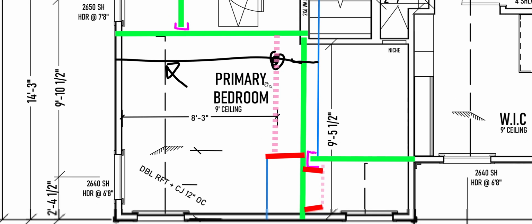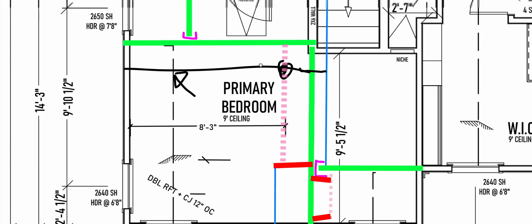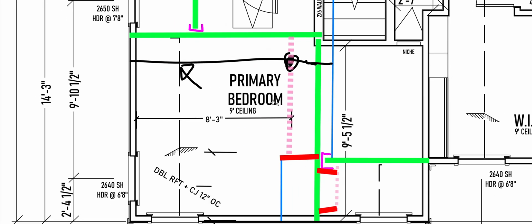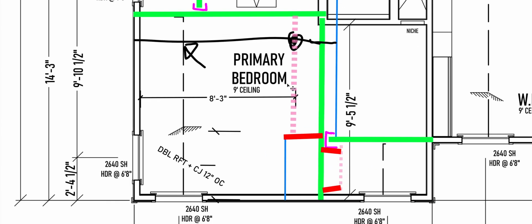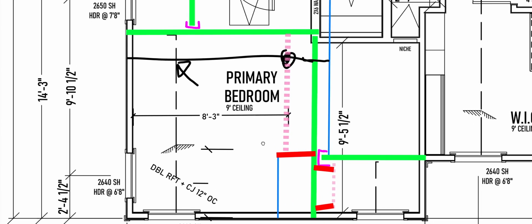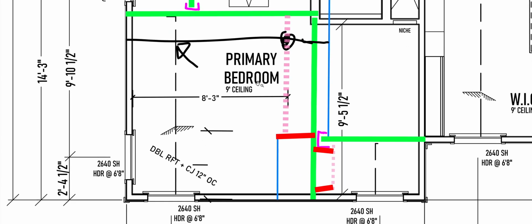It doesn't necessarily have to extend exactly this full distance. At the end of the day, once the rafters are up, I'm going to know which rafters need to be supported because I'm just going to look at them. There's going to be some rafters that aren't supported and some that are. So I just need to do that. Okay. So I'm going to look at this and say, all right, I'm supporting my rafters here. So I'm going to continue this purlin line.